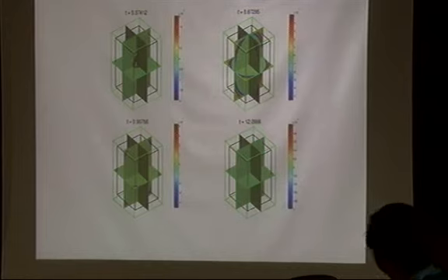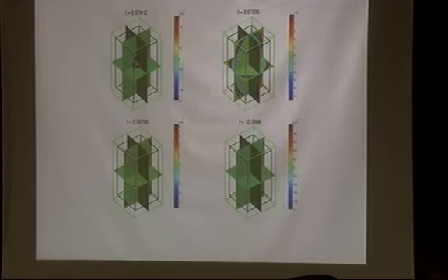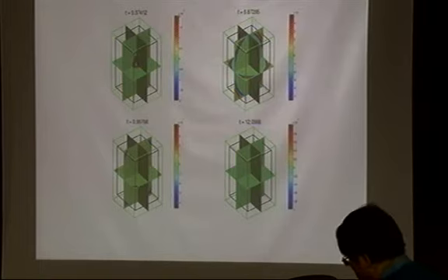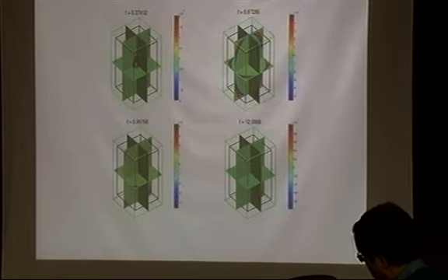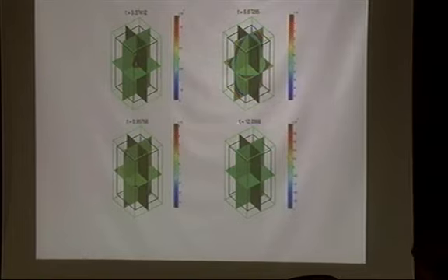In the 3D case here, you can see a source point in the middle of the domain, and here you can see that the green one is the outside of the PML. So on the green one, you put the zero boundary condition, so there is a Dirichlet boundary condition. And then the wave propagates, and you can see that at the long time t equals 12, we don't have any blow-up, so the wave propagates very nicely. So our calculation also verifies stable calculation in this case.